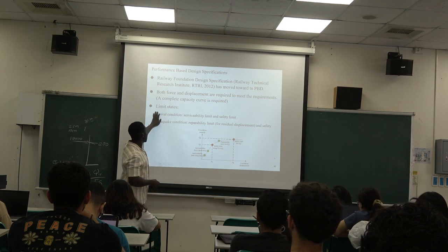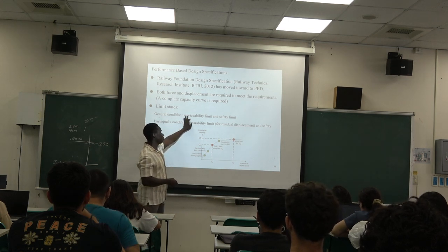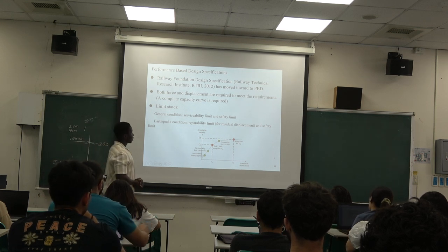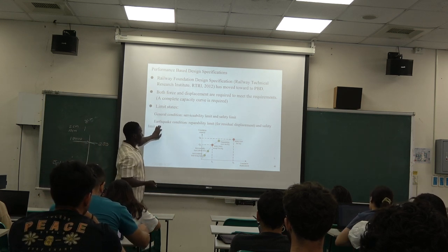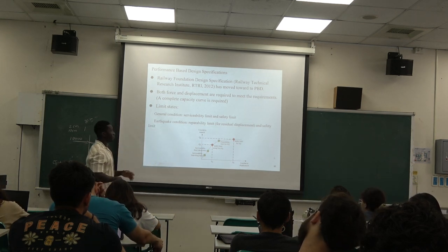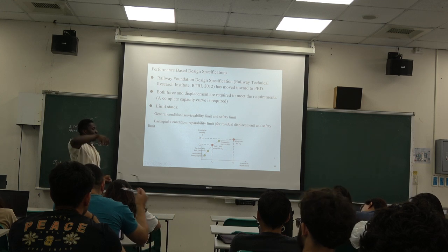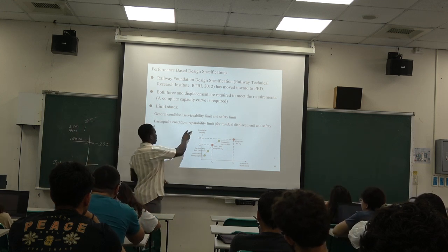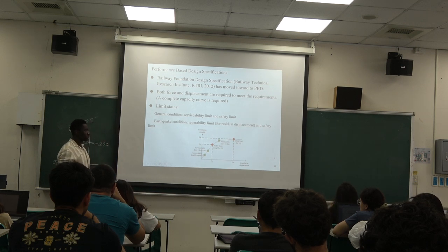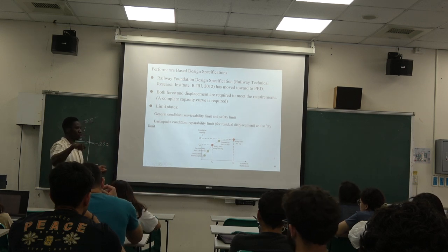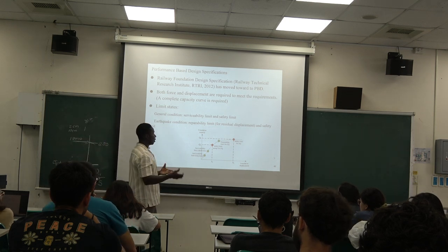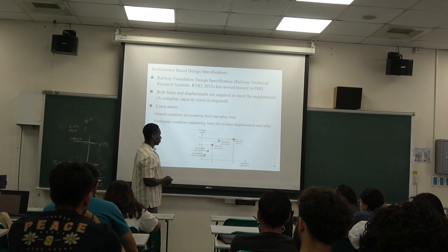Okay, so it says the limit states general condition. We have the serviceability limit and the safety limit. And for the earthquake condition, we have what? Repairability limit for residual displacement and safety limit. So if there's an earthquake condition, for the most part, we can accept repairability. That is to repair some of the structures. Some damage might happen, so you might provide some support to your columns or do a minor repair work on your structure.